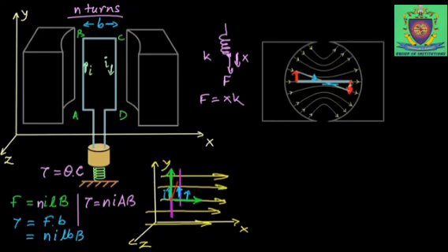So at the BC and at the AD, whatever the force which is acting, both magnitudes are equal and in opposite directions. In the initial stage, the angle between them was zero. Later, when it moves from here to here, it forms an angle and creates a force, but whatever force is created is equal and opposite. Therefore, at the point BC and at AD, both are opposite. See the arrow mark there, it is upwards and this is downwards. So whatever the force created there cancels each other.